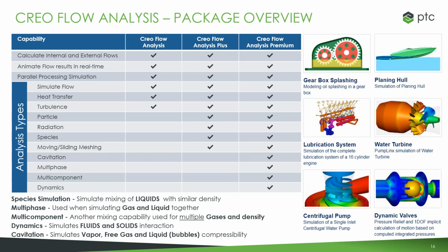However, a lot of our customers are doing somewhat simpler stuff, electronic packaging and heat flow analysis, which would include, by the way, natural convection. I don't think we saw an example of that. This tool does natural convection just fine. You just have to give it a density gradient and it goes off and everything works good.